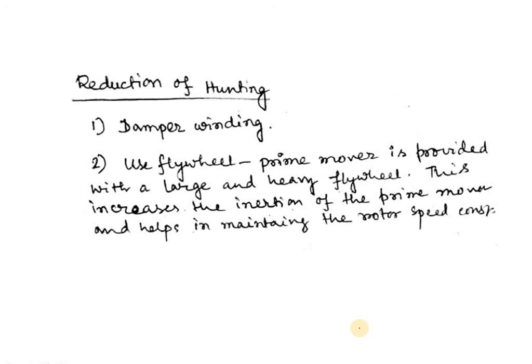of synchronism. In salient pole machines, hunting is reduced by providing damper winding. It consists of short-circuited copper bars embedded in the pole faces. When hunting occurs, there is shifting of armature flux across the pole faces, thereby inducing currents in the damper winding. Since any induced current opposes the action that produces it, the hunting action is opposed by the flow of induced current.